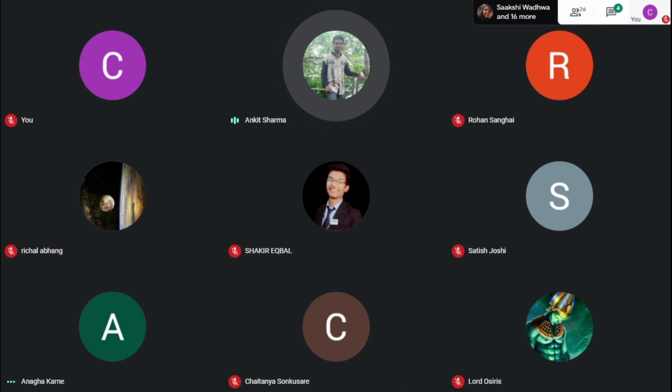Yeah, so our ground station would be a bit multi-purpose, which I have proposed. In that part, since Pune is a city, I selected low noise, low loss cables, which is RG216. How I did the calculation was I checked what people are experiencing in Pune. I had a chat with many people around about their noise levels, what basic noise bed level they experience.